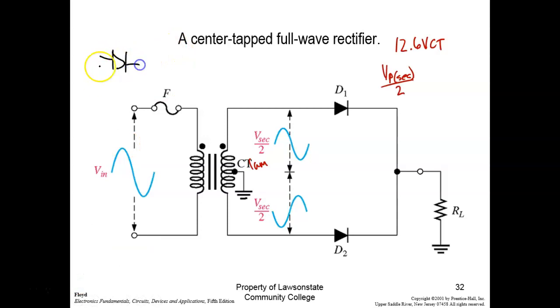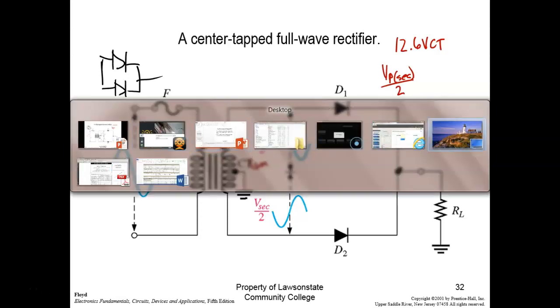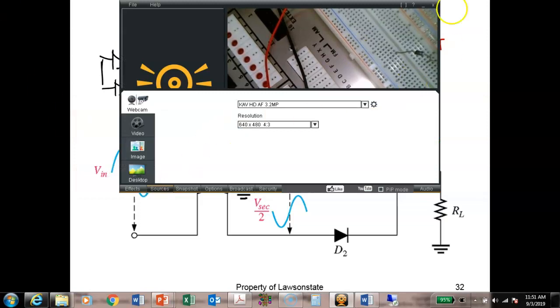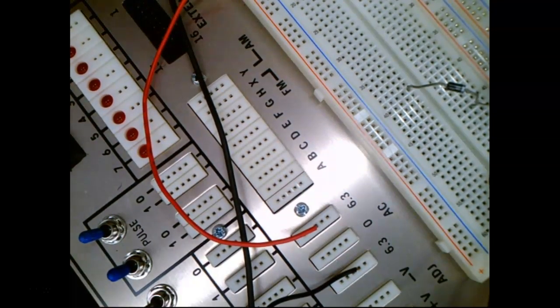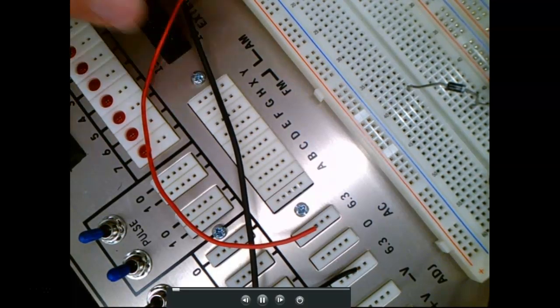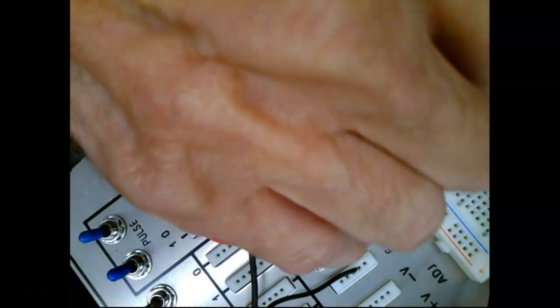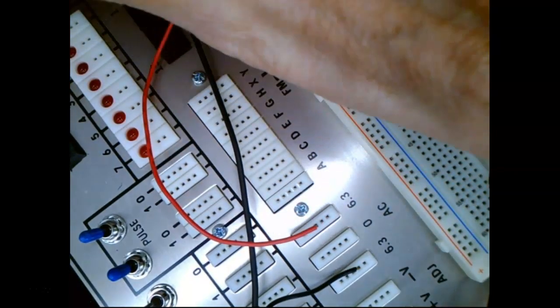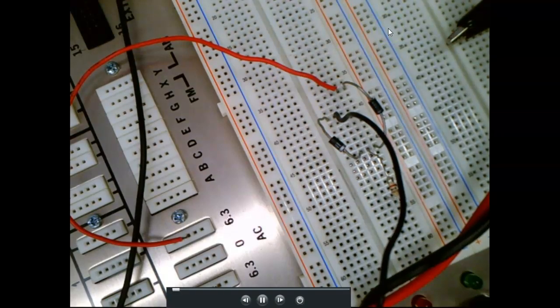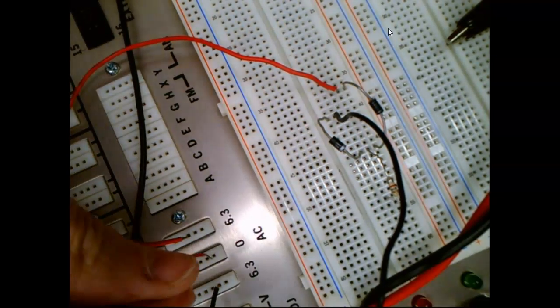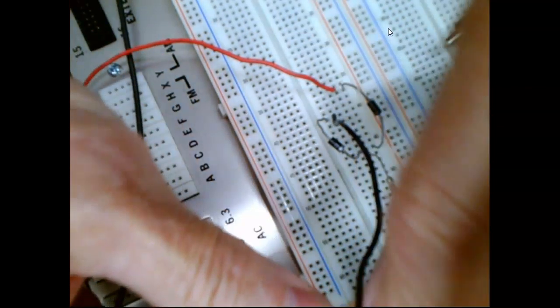So parallel would be this. Parallel means they would have to be connected together. Here the cathodes are connected together, but the anodes are not. So this is not parallel. So what I'm going to do is come up here on my trainer and connect the cathodes together, so we'll make a positive supply. So here's one of my diodes. What did I do in my other one? Dang it. I'm going to take my common and hook it up to the bottom of the resistor, right?